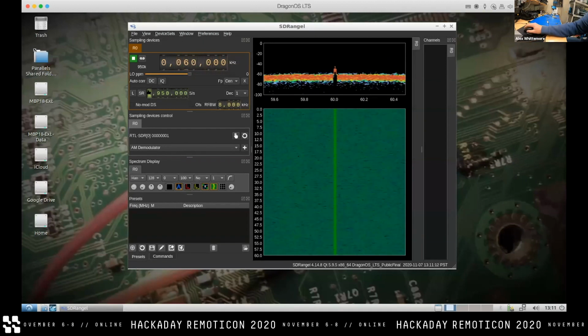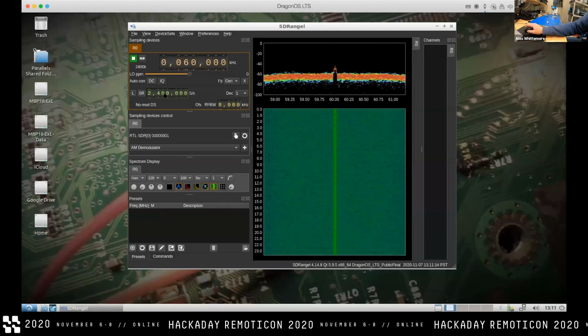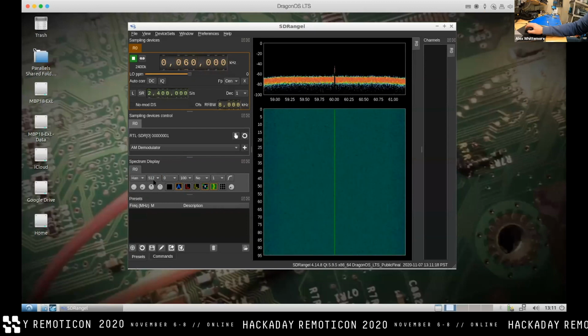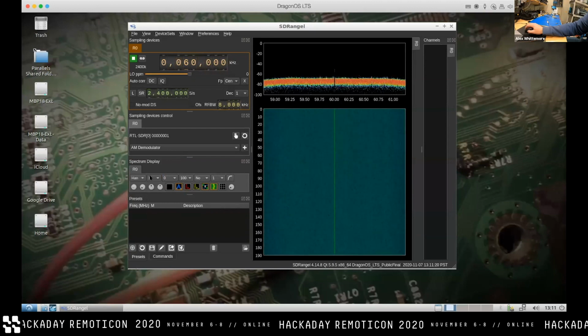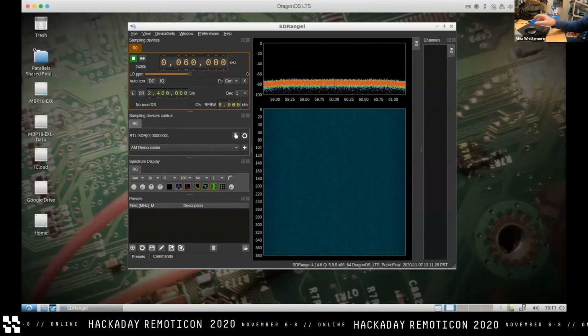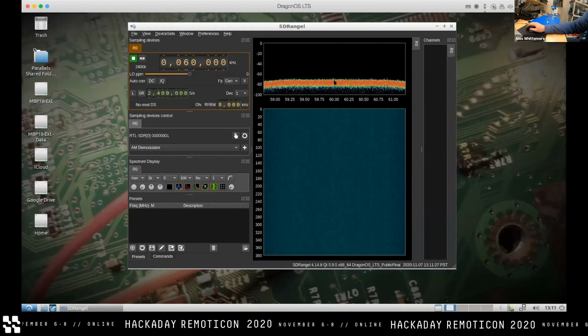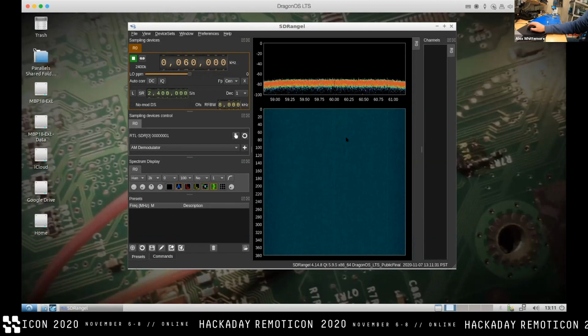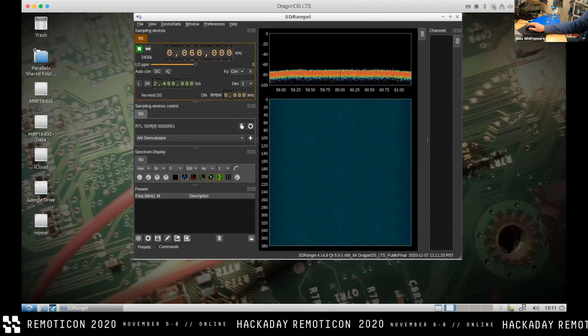And I'm actually also, I know this VM can handle it, so I'm going to crank up the sample rate and everything. And we'll add some FFT bins. This still seems pretty performant. 2K. Okay, cool. Actually, this is an interesting point. When I cranked up the FFT, that peak got very much narrower. So it's probably some unsuppressed artifact of the math or something that I'm just not quite understanding.